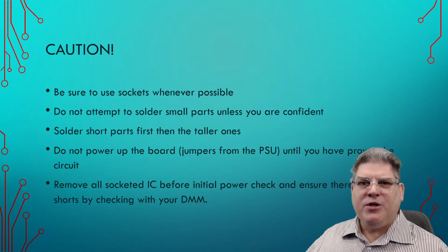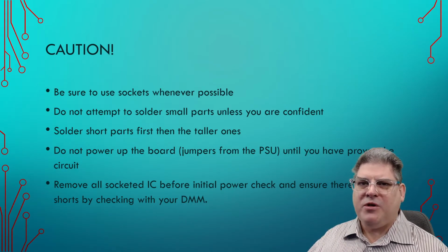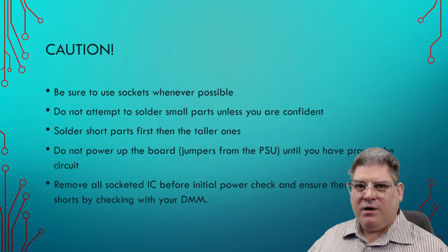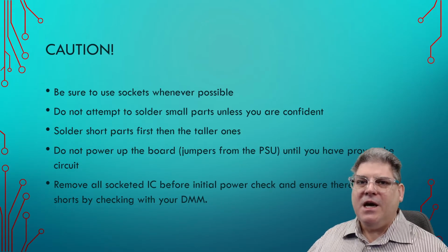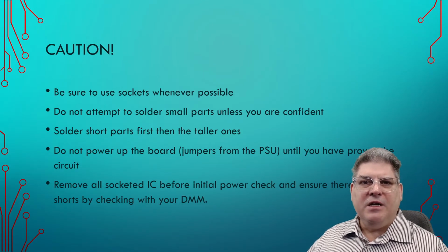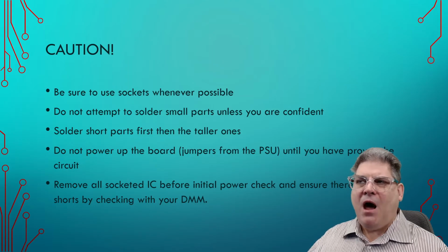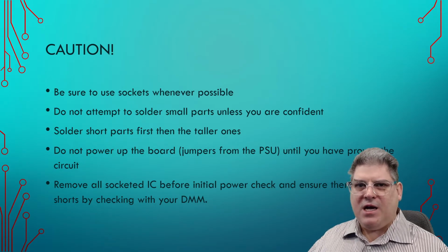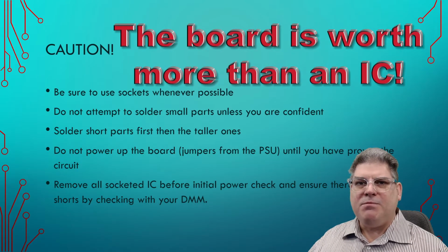Whenever you have the opportunity to put in a socket, especially on a development board, absolutely do that. There's very few times that you'll wish that you hadn't put in a socket, but should you make a mistake while soldering, being able to remove a socket as opposed to an expensive IC is definitely an advantage. As a matter of fact, with things like a 28 pin DIL package, if I have a socket in there, I may not even try to remove it discreetly, I may actually just take the side cutters and cut it off and remove each pin individually, as opposed to trying to desolder each pin.